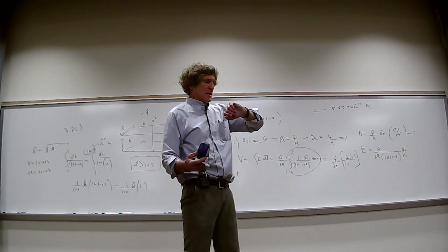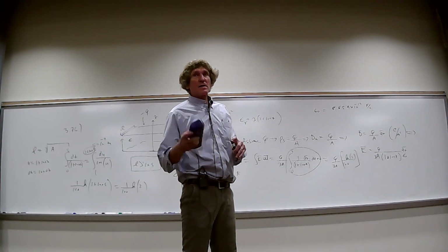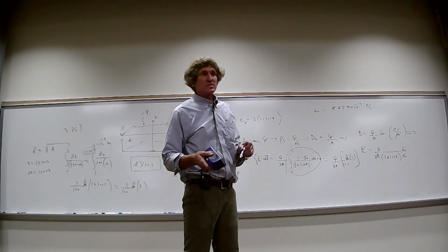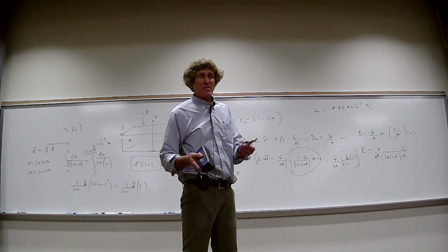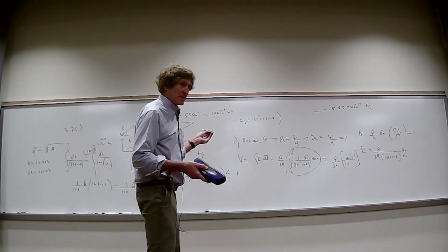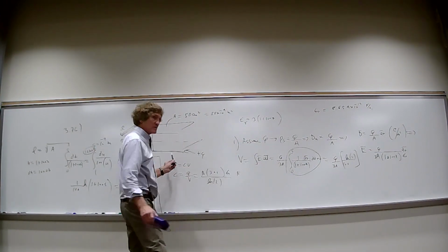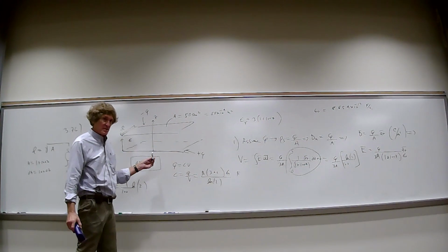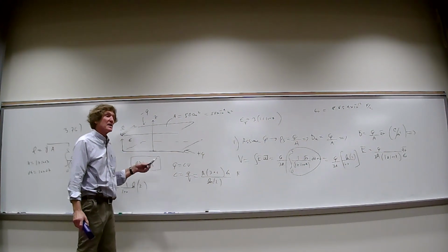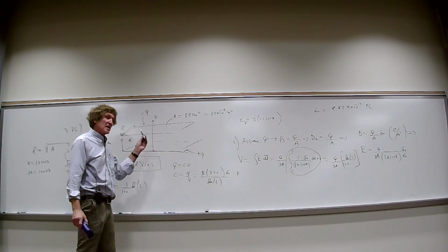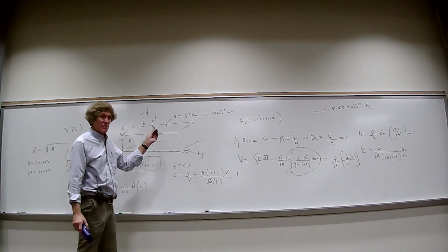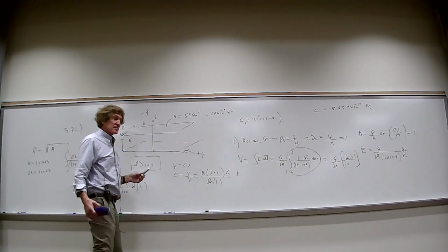That's the method used. Let me just do one thing. I wanted to get through boundary conditions. Answer your question, at least in part. That's not a hard problem. The irritating part is he puts it in centimeters. It's just assuming the charge density, get the E field, and integrate the E field from the bottom to the top plate, get voltage, and then Q is CV, solve for C.